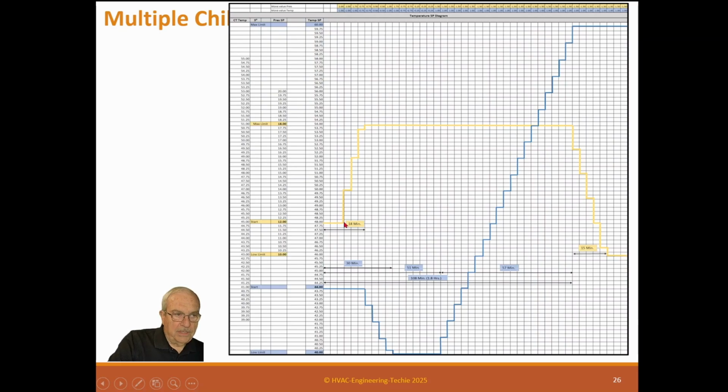But remember, in our sequence we say we limit it until the chill water temperature gets to minimum. Until the pressure gets to maximum, we don't do anything to the chill water temperature. So we're trying to cool everything with this 44-degree set point water. So we apply the resets to the pressure and we let it go up each time. We cycle it, we go up to its maximum of 18 psi. And once we've got there, then it allows the temperature to start dropping.